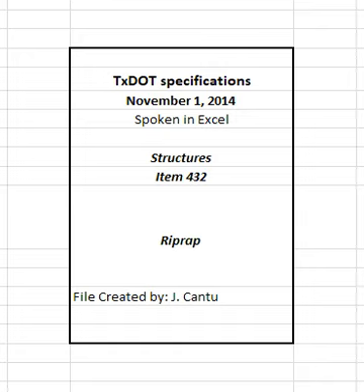Determine the in-place size of the riprap stone by taking linear transects along the riprap and measuring the intermediate axis of the stone at select intervals. Place a tape measure along the riprap and determine the intermediate axis size of the stone at 2 feet intervals. Measure a minimum of 100 stones, either in a single transect or in multiple transects. Then follow ASTM D5519 test procedure Part B to determine the gradation.